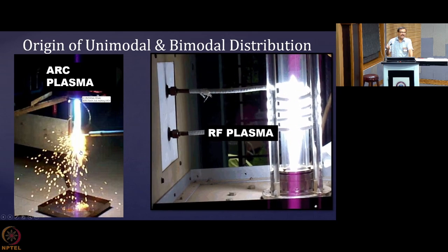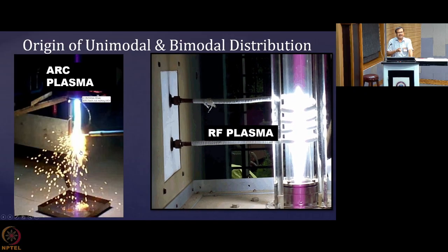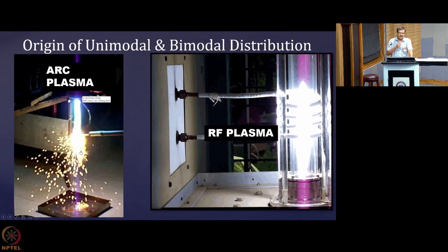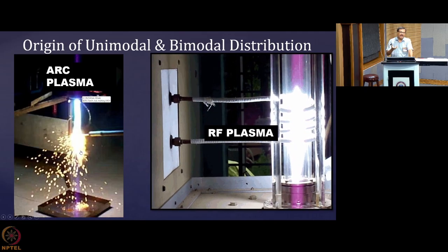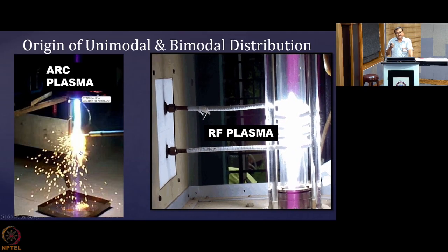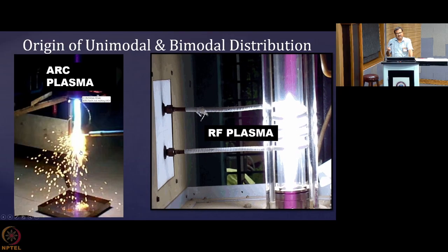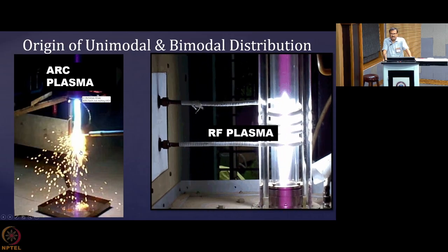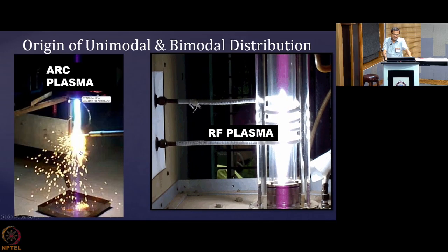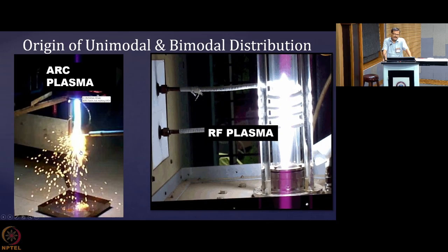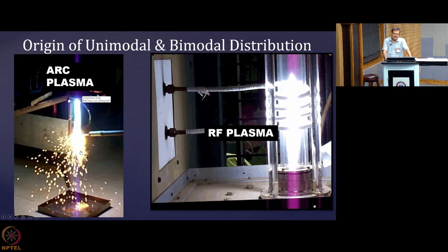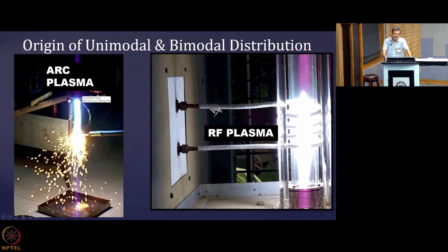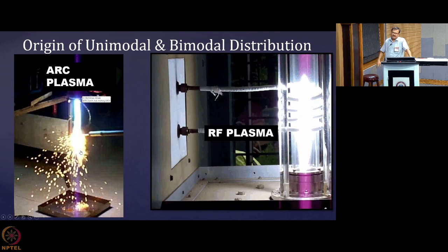growing. The dwell time of the particle within the plasma is quite large comparatively. So because of the higher dwell time inside the plasma, they are getting enough time to collide and grow. So they are finally achieving a final diameter which is much higher than the diameters which are observed when they are nucleated along the radial direction.